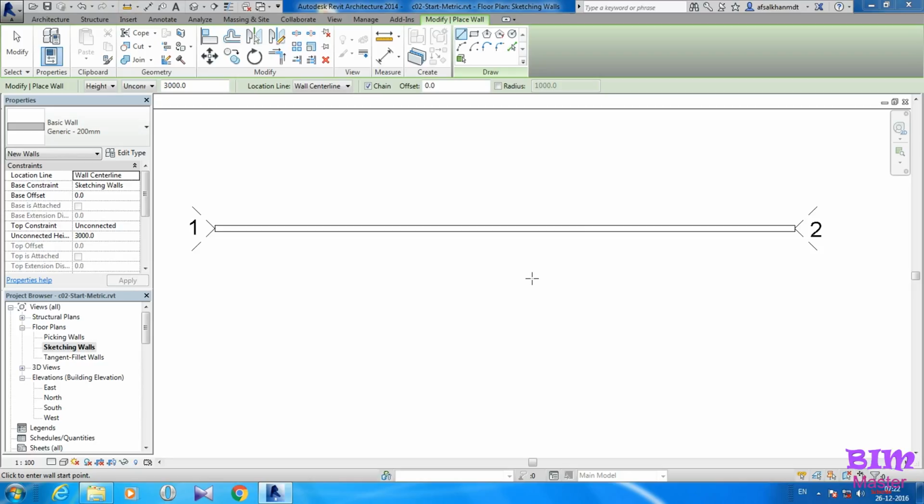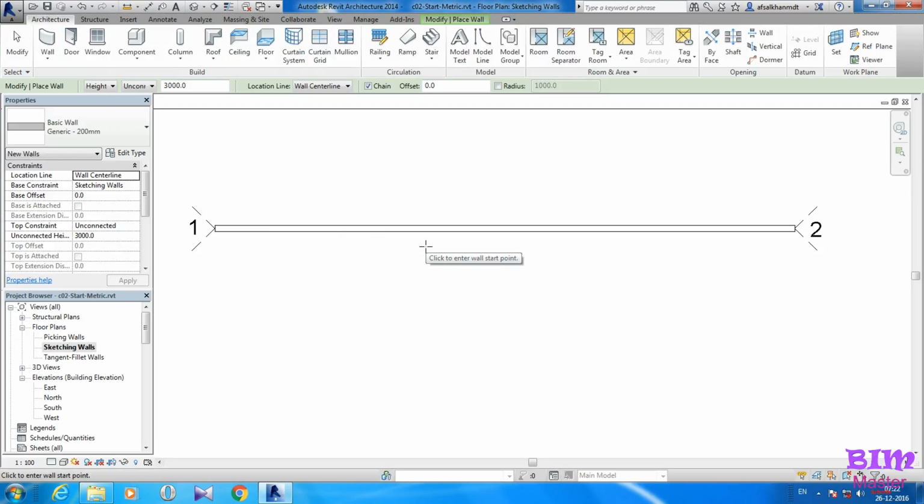Walls can host other types of elements that are meant to create openings. As long as the walls exist, the elements they are hosting exist as well. Doors and windows are examples of commonly used hosted elements. Placing a door in a wall is very easy and can be done in plan, elevation, or 3D view. In this exercise, we will place doors from the Level 1 view.